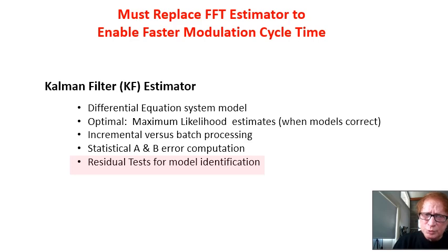Finally, the Kalman filter residual process is the one step ahead predicted error, as you'll see on the next few slides. The statistics of this residual process are well predicted by the Kalman filter. Monitoring the residual process relative to its predicted statistics can be used for model identification. That is, we can detect an unmodeled occurrence, as in the case of an unexpected discontinuity presented by a multipath signal. This may be the most significant aspect of the Kalman filter.